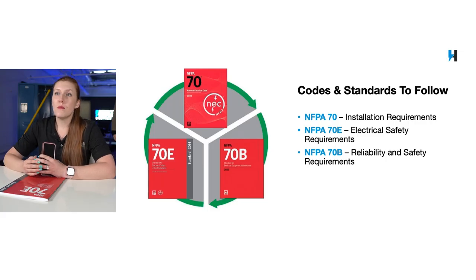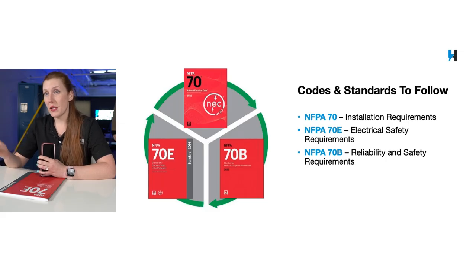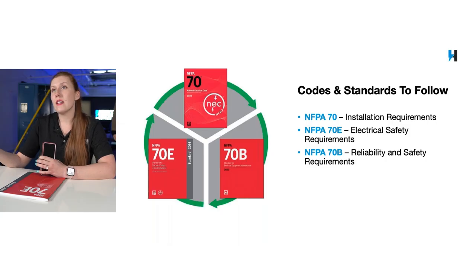So yes, it is multiple standards that we need to follow, not just the NFPA 70E. We've got the installation requirements and the maintenance requirements in the NFPA 70, more commonly called the National Electrical Code or NEC, and the 70B, the standard for electrical equipment maintenance. So you do still have to follow those as well as the NFPA 70E.